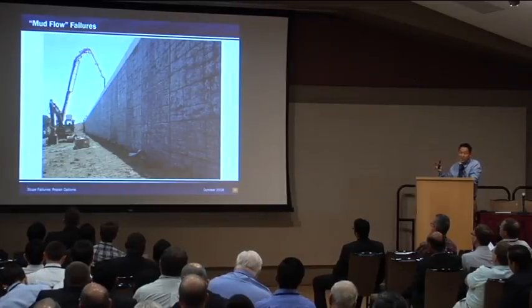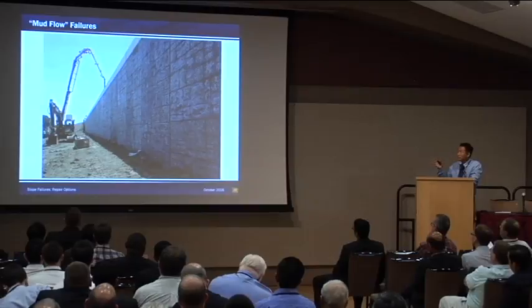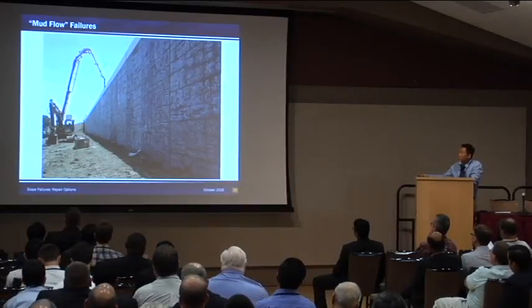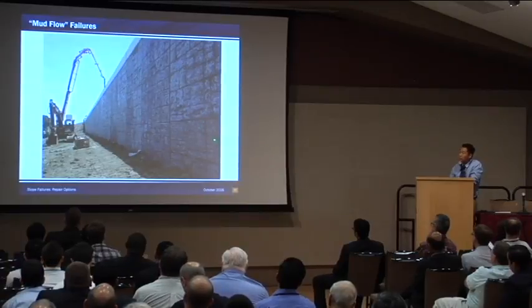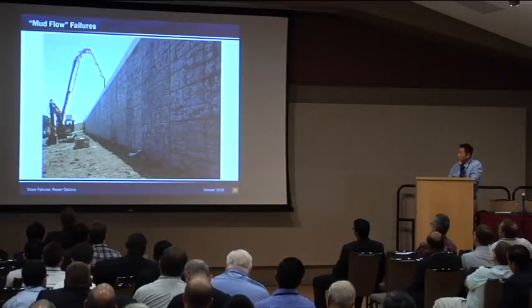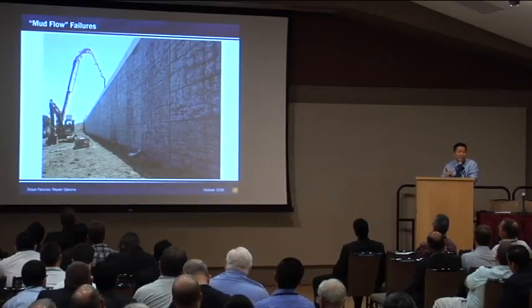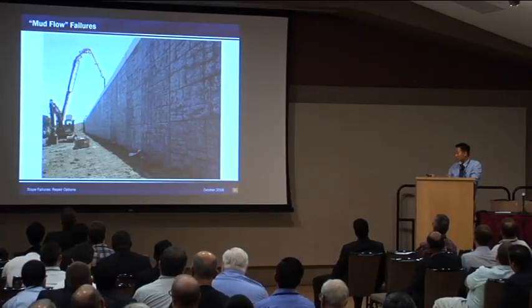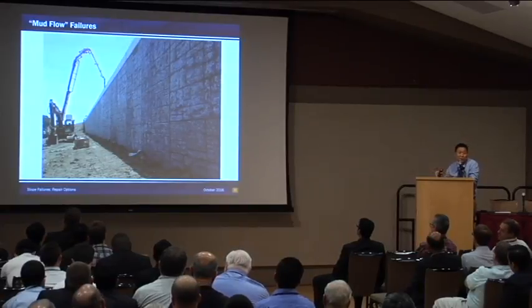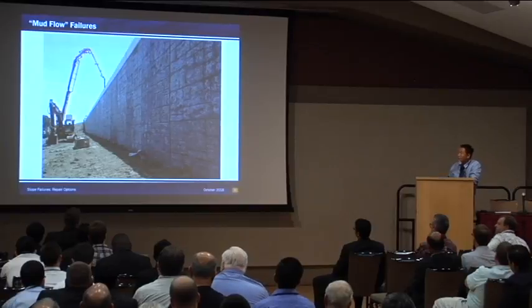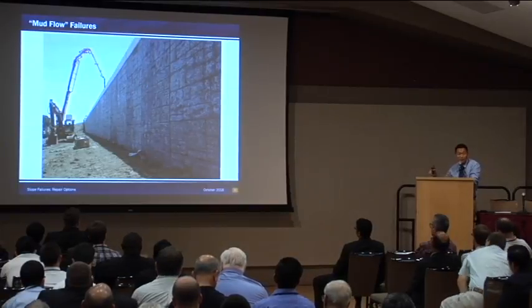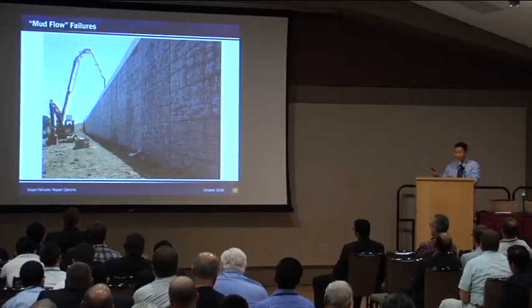So this is the final solution for the slope failure, just before putting in the vegetation and the railing. We installed the soil nail wall, and we put the fascia on the soil nails. This is a sculpted granite fascia, just as side information. The precast panel is the most common, but you can also put sculpted granite. Basically, you shoot down the shotcrete and you can sculpt it, so it's pretty much like architectural construction. The sculptors made this one by one, so you have lots of options to make your work pretty.